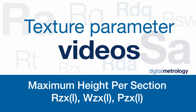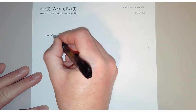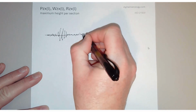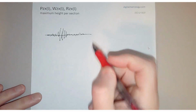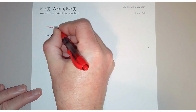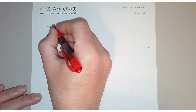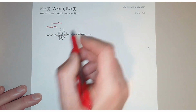Sometimes in surface texture analysis, we want to capture a locally bad region. For example, this surface may have a zone that's rough in the middle, and we want to understand the worst roughness in a zone. That's what the maximum height per section parameter does for us. What we're going to do is choose a section of the surface and calculate the total height in that section, and then move this section along one data point at a time.